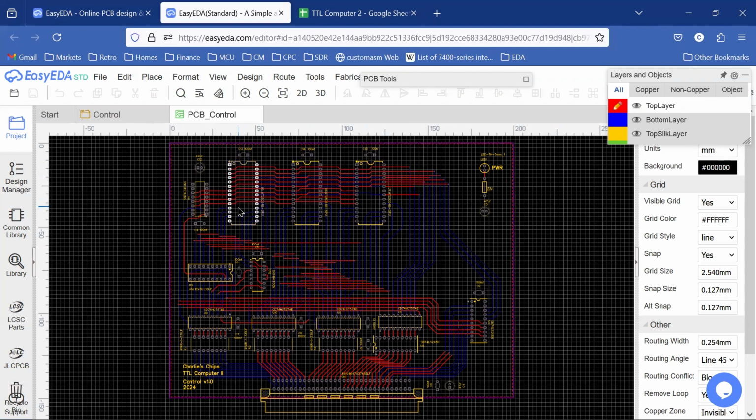You can see that the EPROMs are all wired in parallel to form up bus lines, and then the outputs are brought down. But for now, a lot of these I just implemented the microcode piecemeal as we did the digital build out.